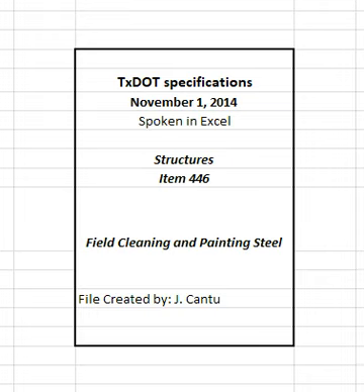2.1.6 System 1V. Provide paint in accordance with DMS 8101, structural steel paints performance. Provide IOZ prime coat and acrylic latex appearance coat. Provide epoxy zinc prime coat, as recommended by the IOZ manufacturer, for touch-up of IOZ.